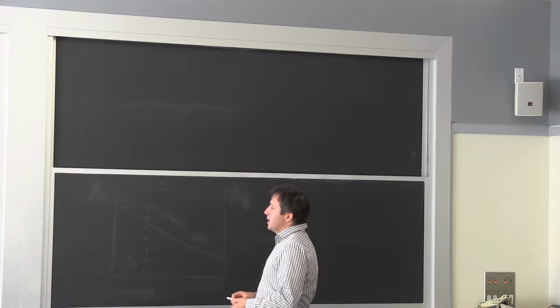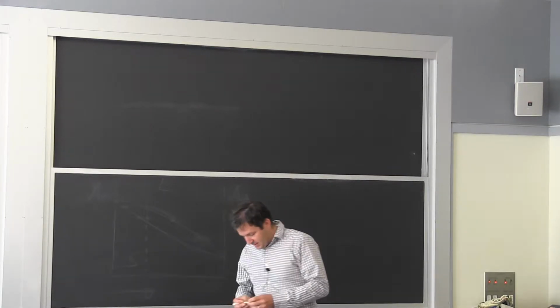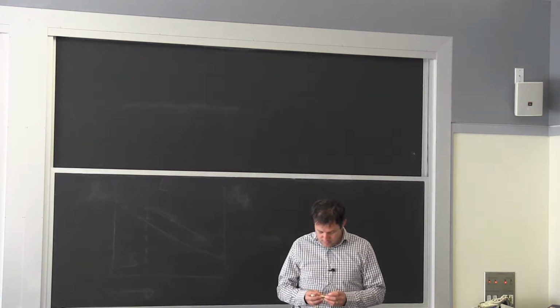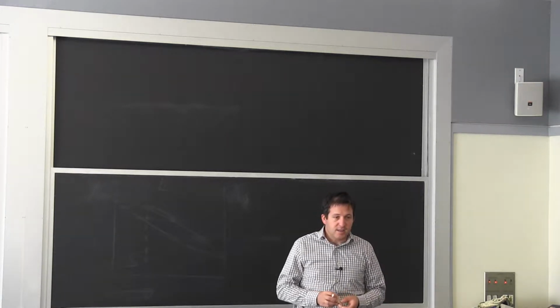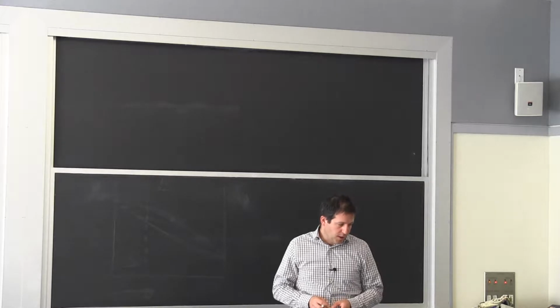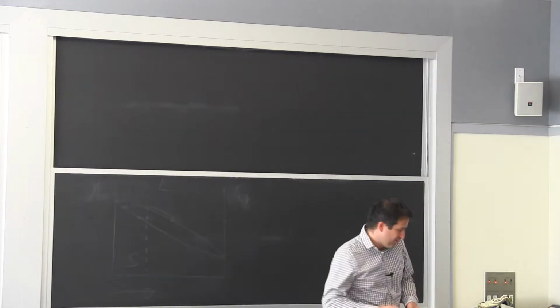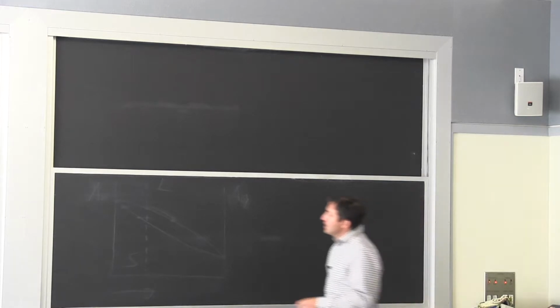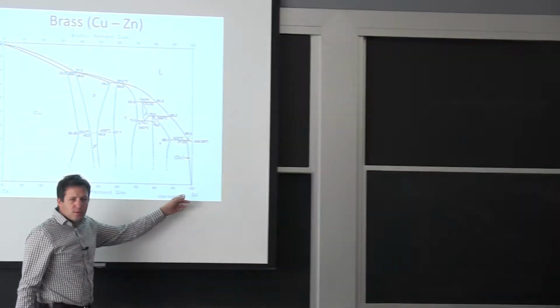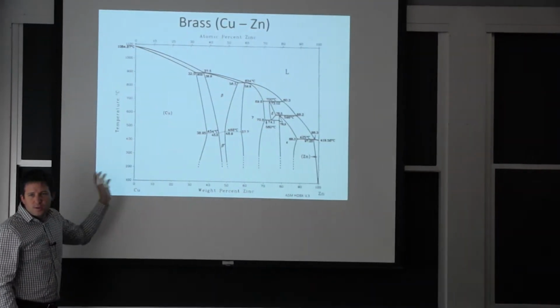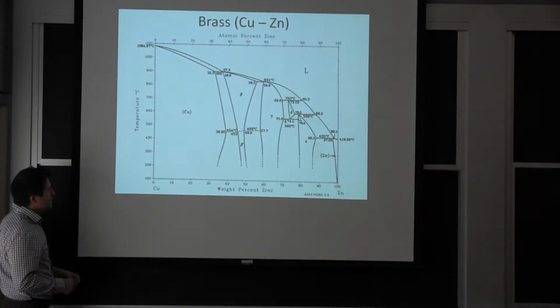Valves, a lot of time are brass, and one of the reasons is it's easy to machine them at relatively high speed and with precision. And the reason is, well, things change with respect to that, but one way, traditionally, where you have this brass here, which is copper and zinc, there are multiple advantages. First of all, zinc is cheaper than copper, so you're reducing your price by adding the zinc here.